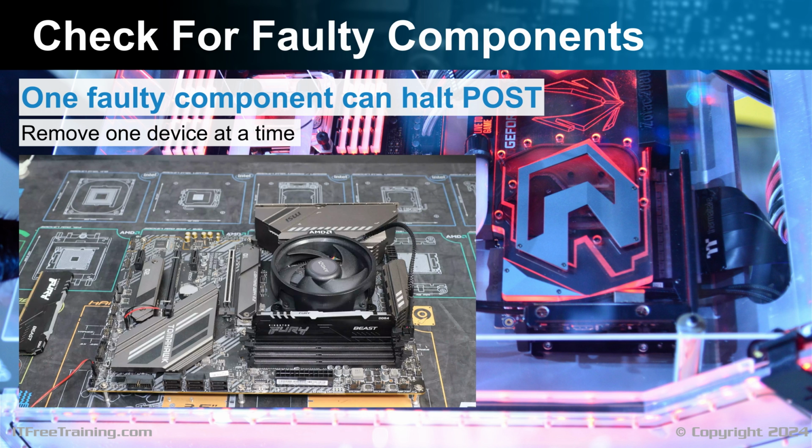During troubleshooting, it is important to consider that a component might not be properly seated, meaning it's not making good contact with the connector. Before concluding that a slot is damaged, ensure there's nothing obstructing the connection and that the component is correctly positioned in its slot. This step is crucial, as improper seating can often be mistaken for some serious hardware faults.